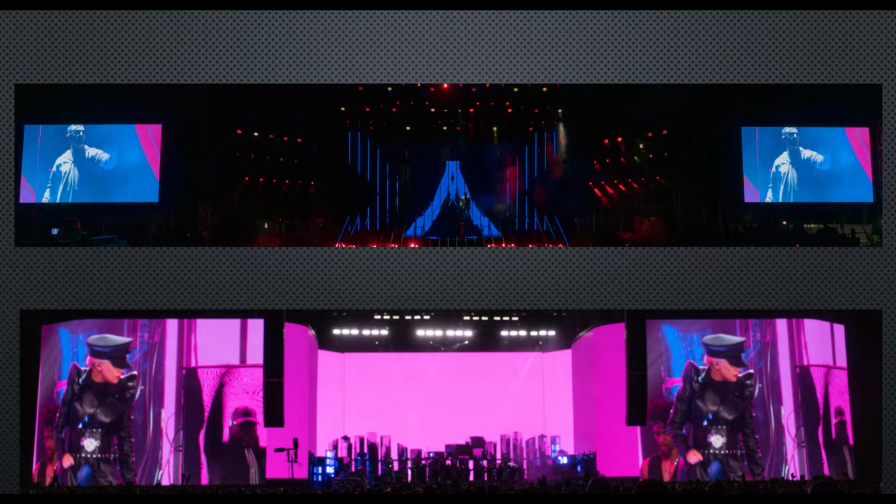This is from a festival called Coachella here in North or South California, and you can see the large display of screen. These are both the exact same stage. You are just not seeing the rest of the screen on the top image, as that's what the artist wanted. They wanted to see the full 16 by 9 image on the LED wall. And that's what we had to do using, again, a Barco E2 switcher, which is now possible using a Nova Pro Ultra HD Junior with multiple layers of windows. In the bottom picture, you can see we've still maintained the 16 by 9 aspect ratio and scaled it up to fill top to bottom and cut off a lot of image side to side, because that LED screen is, again, not 16 by 9.